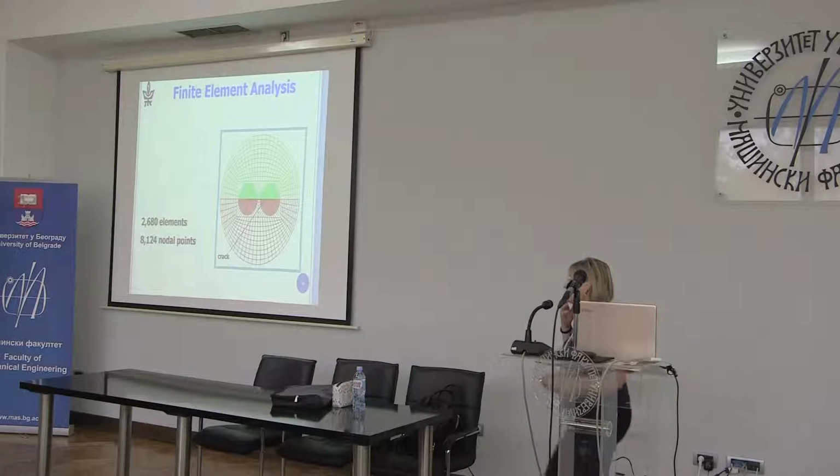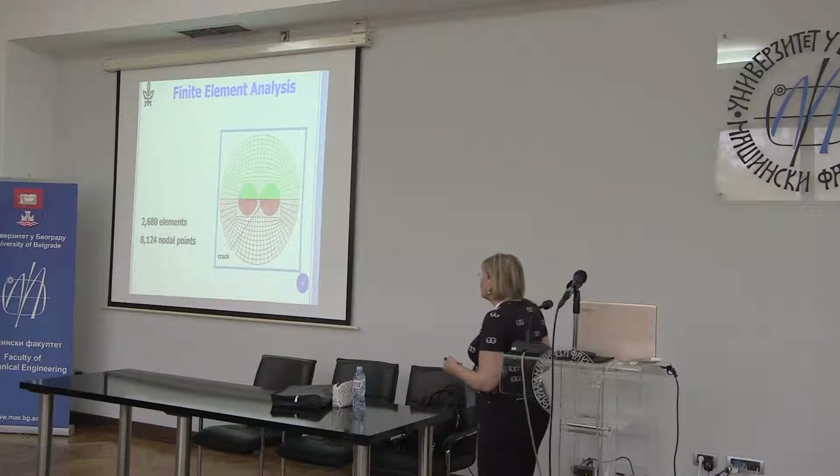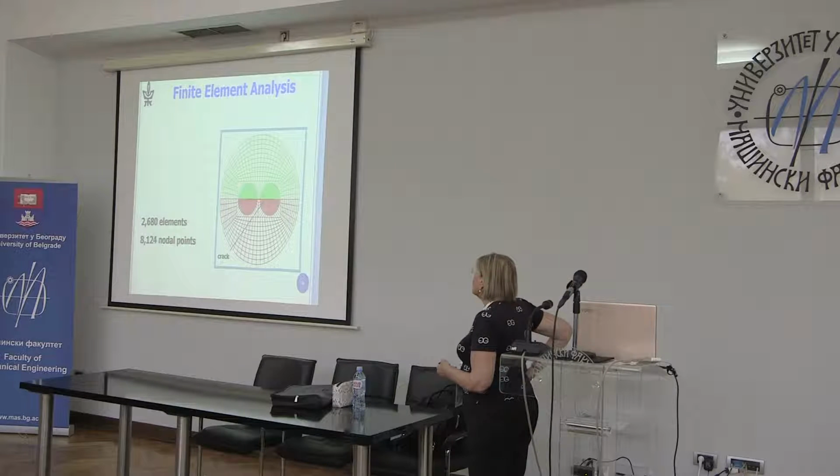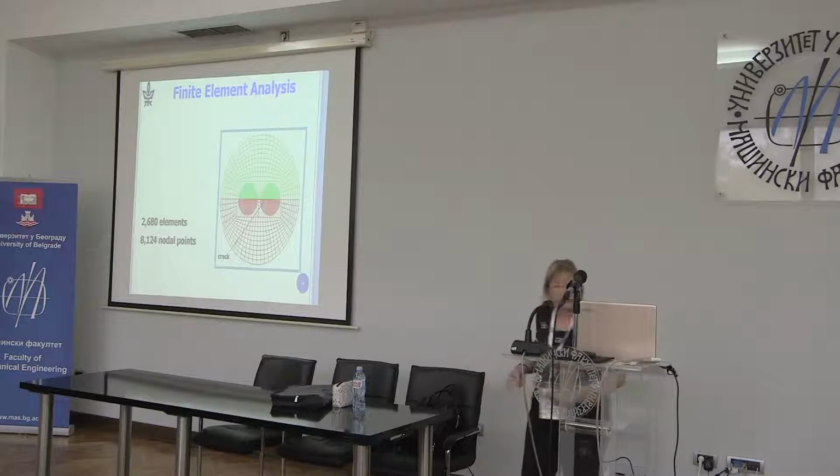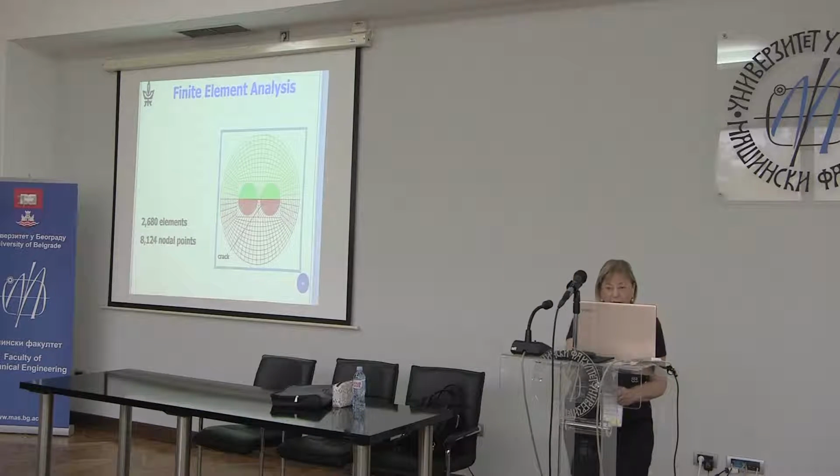So then we want to analyze the specimen. In the finite elements, the specimen was standing so that this was the crack, this was the interface, and we were loading in this direction. For finite elements, it's easy just to put the interface here, and you load in this direction or in this direction. These were the finite element meshes for one of the analyses.